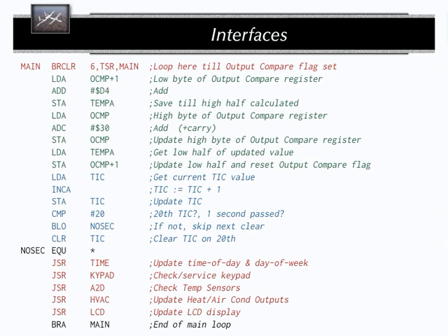And this is a classical pattern which you often see in these microcontrollers. They're not suspending themselves, there's no task switching, there's no context switching. You're actually staring at an I/O line until something is happening, and you're staring with the full might of your CPU at this I/O line until this thing changes. Brutal, very effective, easy to predict.